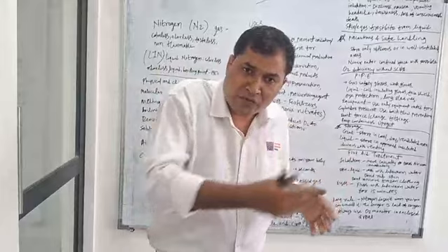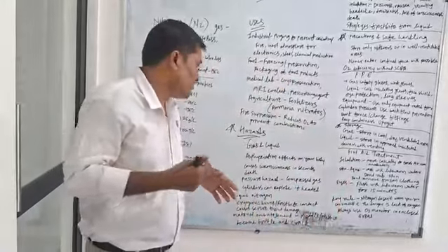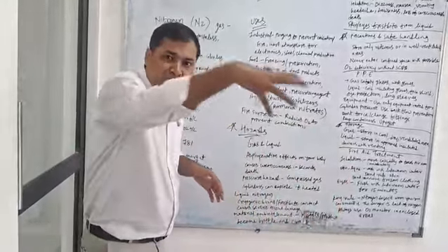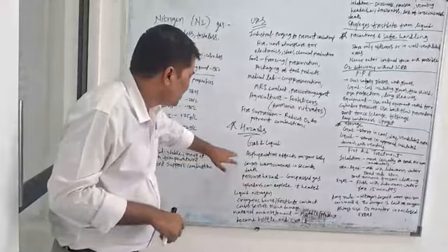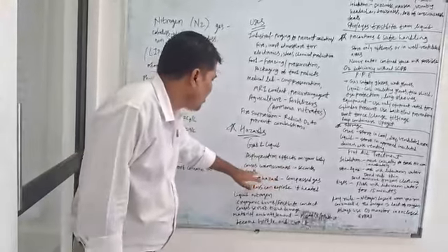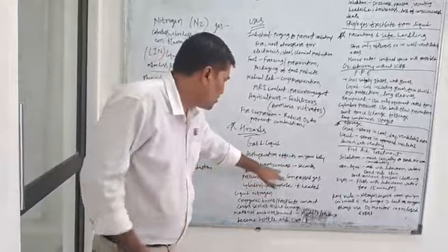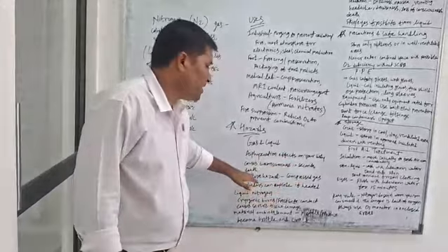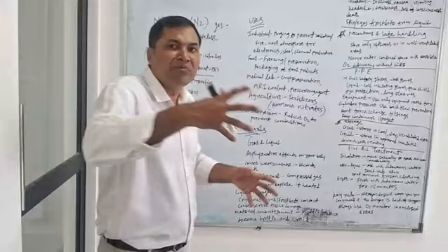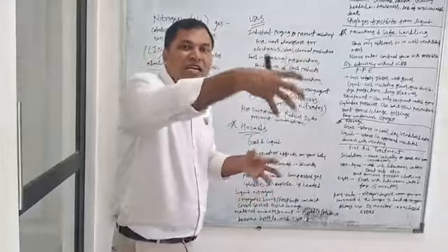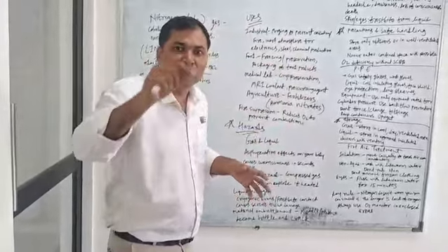Okay. So it is better to move out from that area. Never stand in the same area where you purge the nitrogen. It has an asphyxiating effect on your body and causes unconsciousness in seconds, or maybe even death, if the nitrogen level there is at maximum concentration and the oxygen is 0%.